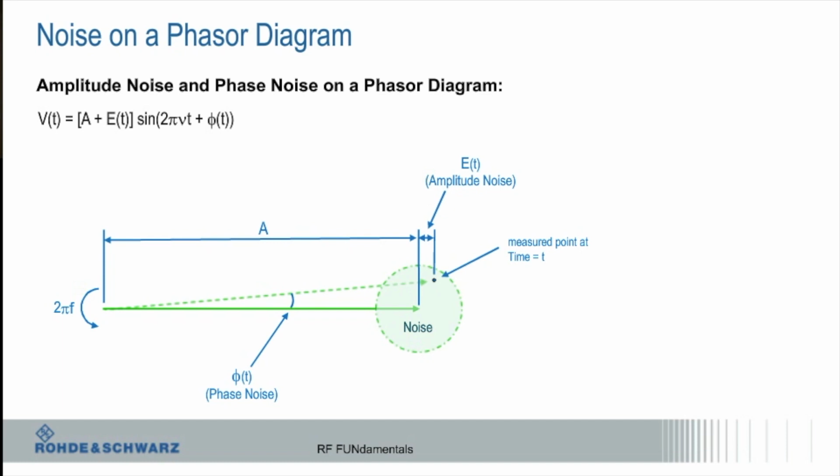Then there's an amplitude error term, which is the length of that vector changing. So if you take those two in combination, that point, which is the dot or the constellation point, is going to kind of spread out in space because it's rotating a little bit back and forth, and then its amplitude is getting varied also, so that dot gets bigger.